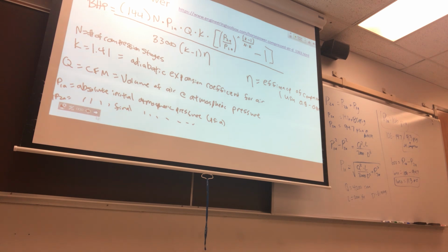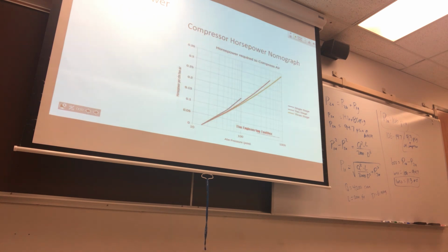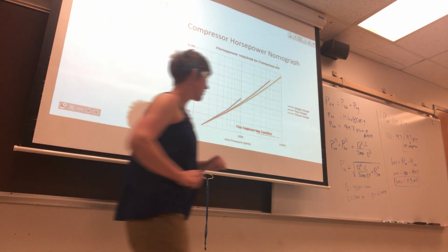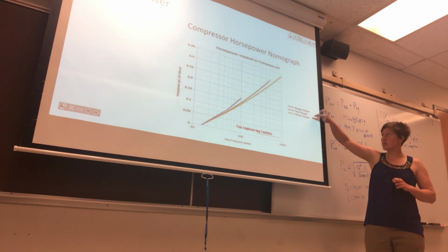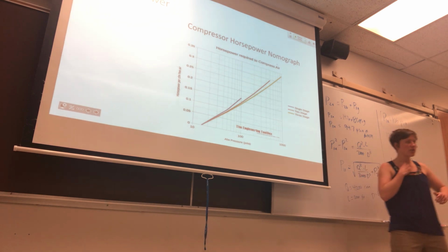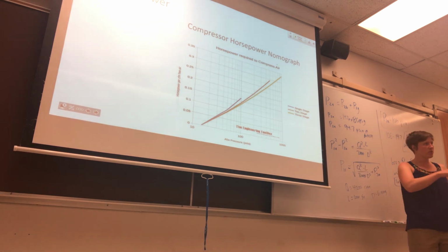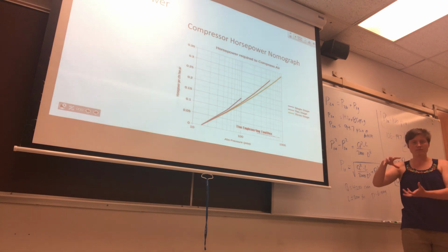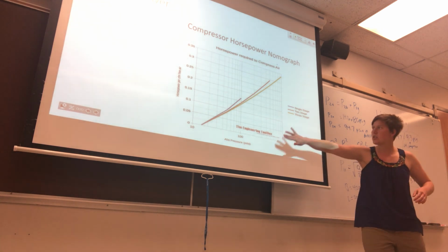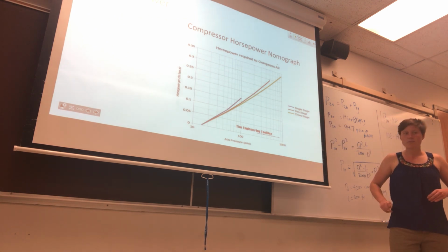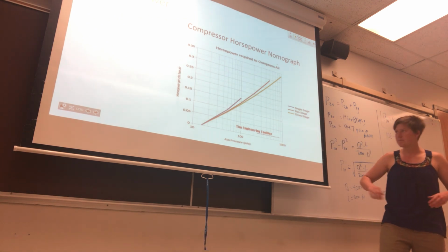On that website, they show you the curve. They use a nomograph. And so that big N term that we were talking about, they have different plots for if you have a single, a two-stage, or three-stage air compressor. And those are basically the number of chambers that you have in order to compress the air. So there's these different curves that they have theoretically and experimentally proven.